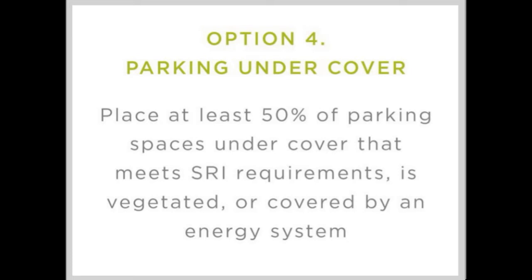The performance requirement to implement this credit is a maintenance program that ensures all SRI surfaces are cleaned at least every 3 years to maintain good reflectance, and all vegetated roofs are maintained for plant health and good structural condition.